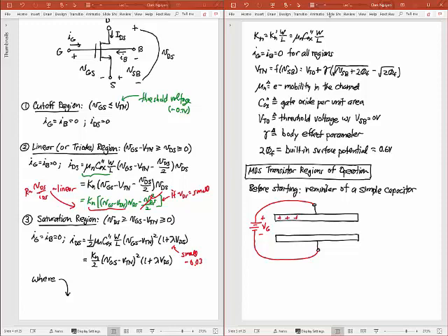If the positive terminal of VG is there, then I just put some positive charge on the top plate, and I'm putting some negative charge on the bottom plate. That's all that's really happening in a capacitor. I've induced plus Q here. I've induced minus Q here, right? So the plus Q there, you could say, induces the minus Q, or they induce each other, right? They're both induced by the voltage, and this minus Q is going to be equal and opposite to that plus Q. You always have to have this, right?